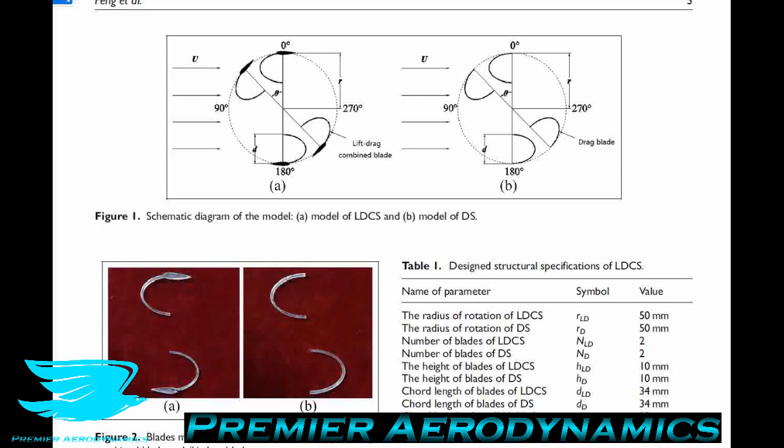Also, these blades have a NACA 0018 airfoil profile. This is the one that they're using. This profile is quite thick, which means that they will stall at a higher angle of attack and have a more gradual stall pattern. So that means that we have a bit more of a buffer in terms of where we can use them. If we had a very thin airfoil, for example a NACA 0006 or even lower, like 0002 maybe, then when we go to a moderate angle of attack like 5 degrees or 10 degrees, the airfoil will stall, and that means we don't get lift, which is not great.